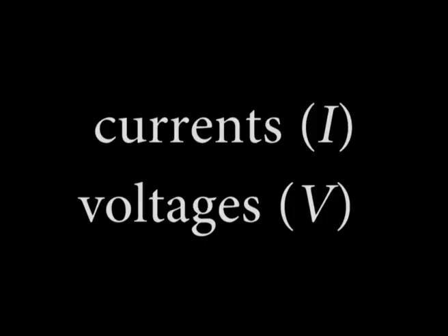DC and AC quantities. Before discussing the concept of transistor amplification, the designations that we will use for the circuit quantities of current and voltage must be explained, because amplifier circuits have both DC and AC quantities. In this lecture, italic capital letters are used for both DC and AC currents and voltages. This rule applies to RMS, average, peak and peak to peak AC values.